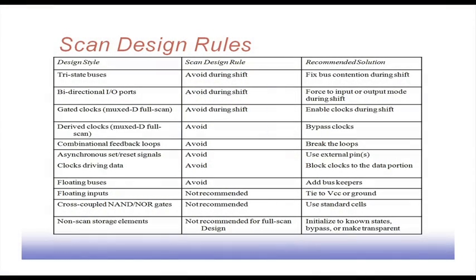As far as scan design rules are concerned, there are several design styles that create difficulty while we are putting the scan on top of them, and they have to be corrected or the design has to be modified, like the tri-state buses. Many of our designs have tri-state buses. The scan design rule says that tri-state buses be avoided during shift operation, because if some bus is tri-stated, then the pattern will not shift through that bus.